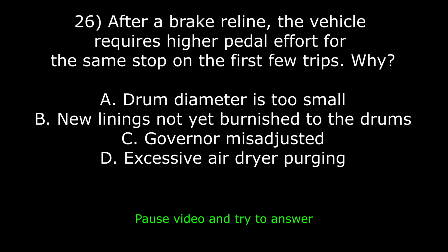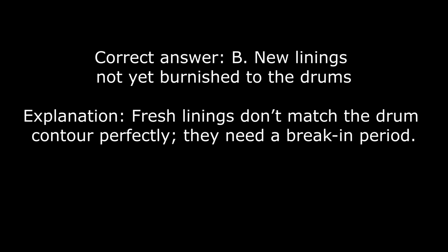B. New linings not yet burnished to the drums. C. Governor misadjusted. D. Excessive air dryer purging. Correct answer? B. New linings not yet burnished to the drums. Explanation: fresh linings don't match the drum contour perfectly. They need a break-in period.